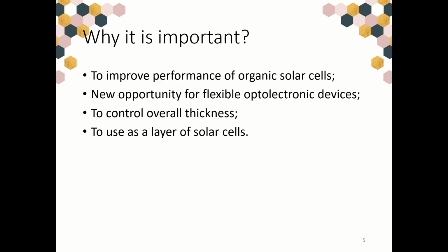So, thin film deposited by angle deposition have the following characteristics. The films are in general porous. The nanocolumns are tilting away from the surface normal to the incident evaporation beam direction. The size and the density of the nanocolumns change as function of the incident angle. It is one of the reasons why it is important.